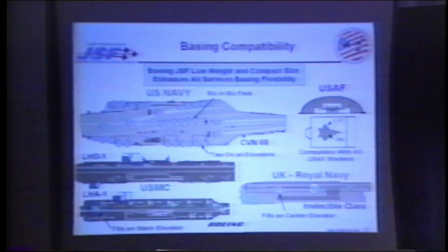And then in terms of how the airplane stacks up for basing modes, as we said before, a lot of these service unique requirements are associated with different basing modes. With the compact common design we've defined, we do an excellent job of meeting the different basing requirements. On the CV big decks, we do not require a wing fold on the airplane. We have a spot factor of less than 1. Without that wing fold, we can position 2 aircraft side by side on each elevator, as well as 6 in the 6-pack without that folded wing.